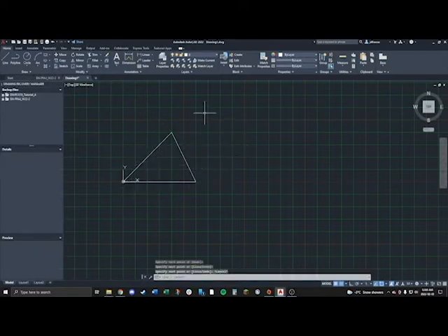And if I wanted to make a triangle, I can just close it. And from here, if I want to check any of these points, so if you've been given a point, you can always check it by going to Utilities and dropping down to this button called ID Point. ID Point will give you the exact coordinates of any location. So I can see here 0, yep, 60, it's 40, 40, exactly where we want it. And that is the easiest way. Always check your start points specifically.